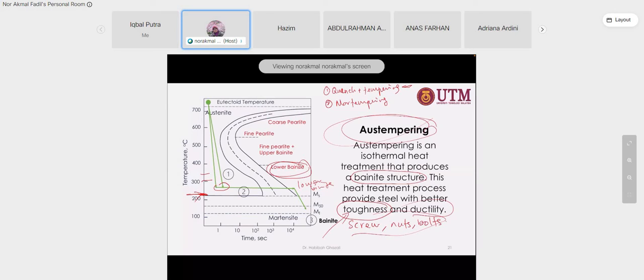Because the structure is small, whatever temperature effects they experience from the outside temperature to the 200 or 300 something temperature, they experience a real quenching process, like a martensite formation, because of the very large temperature difference, and the small component has a small volume. So it can utilize this kind of austempering process.